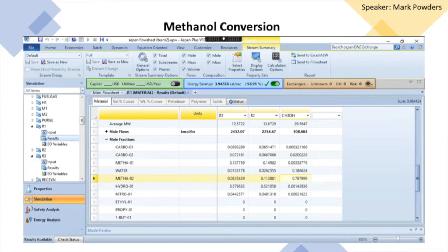The reaction of syngas to methanol is exothermic, which means that a considerable amount of heat is released as the reaction proceeds. Hence, the effluent stream from the first reactor was decided to be cooled down before being sent to the second. In line with Le Chatelier's principle, the forward reaction is favoured, and therefore a high conversion was achieved.